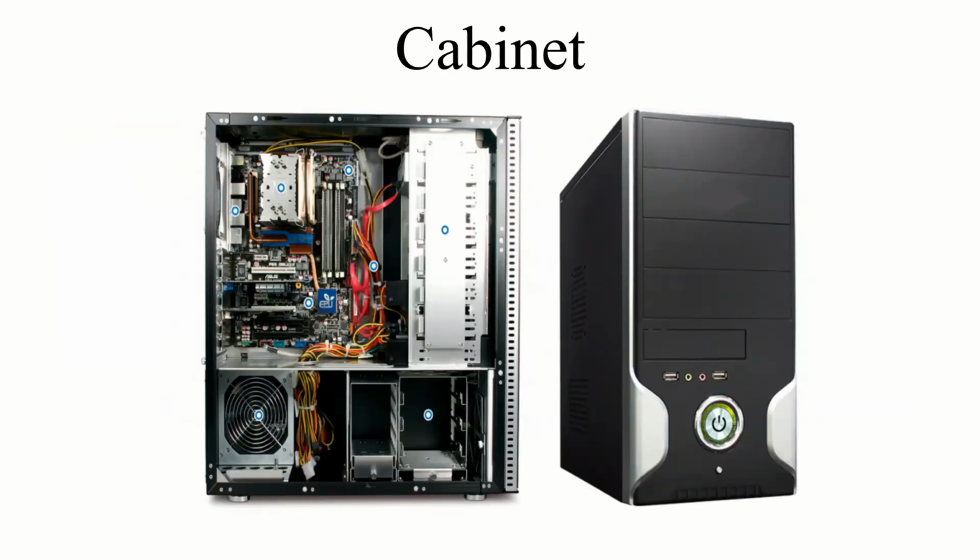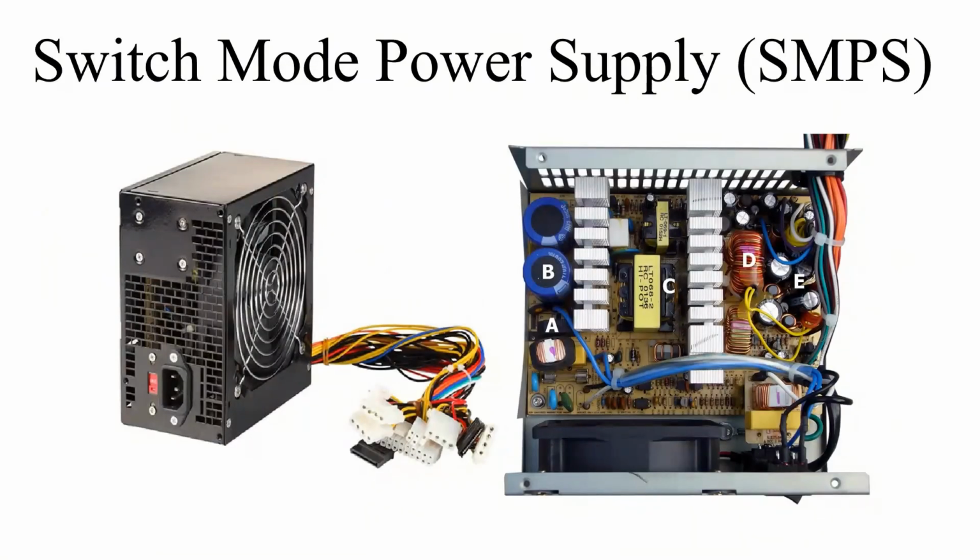I can show you where this is in the SMPS section. See, there is one green cable coming in here, and the black one is there. We need to put the pin on that green cable slot and the black cable slot, and power on the supply. If power is coming on the SMPS and the fan is working, then it could be an issue with the motherboard.